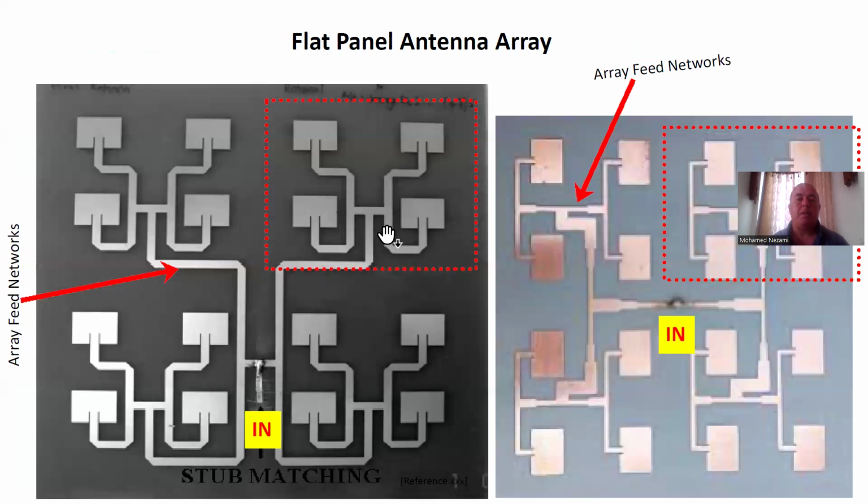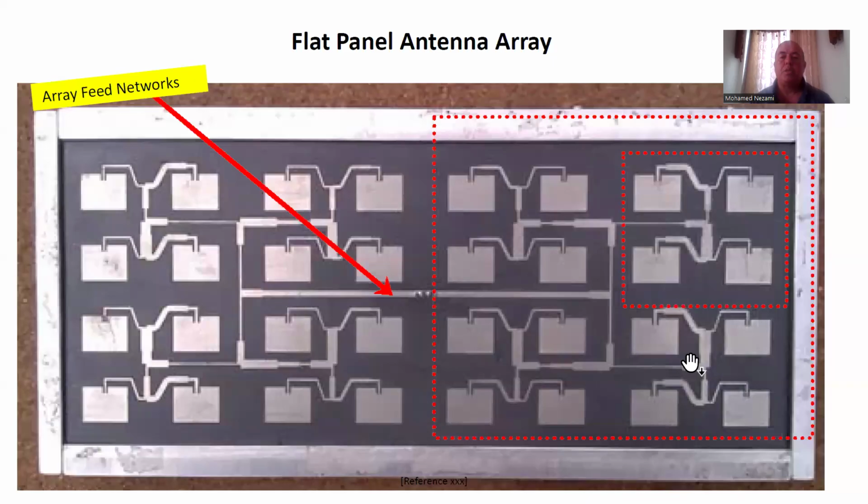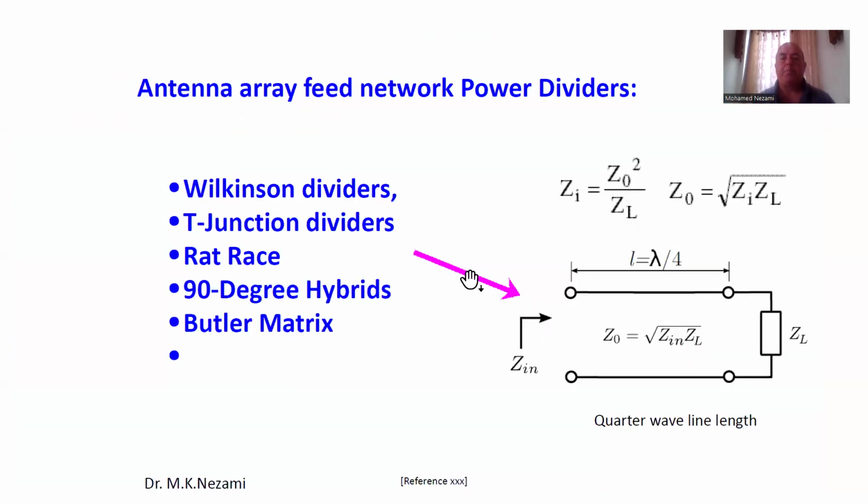You can see here that the signal gets split and is equally distributed to all of these antennas. While in other ones, like this one here, you can see that there is a pattern where some lines on the T-junction are narrower than the other ones. And so you can see that there is a tapered distribution in here because the amplitudes are not equal.